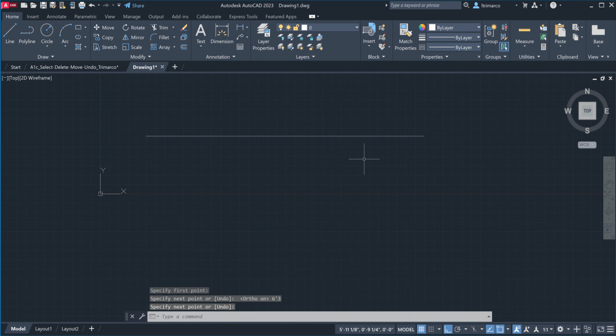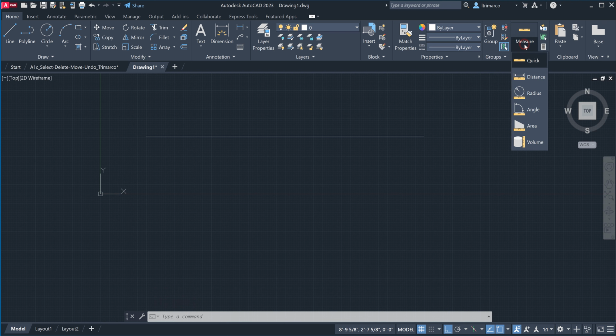Now, how do I know? I remember long ago drawing in AutoCAD and thinking, how do I know that's right? This is where, again, under the Home tab, all the way to the right under Utilities, let me hit escape. When you're stuck, ever, hit the escape key in the upper left-hand corner. So constantly I'm drawing in AutoCAD with my right hand and my left hand. But at the top, under the Utilities panel, go ahead and pull down the menu under Measure.